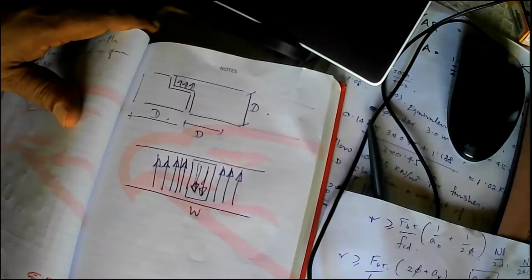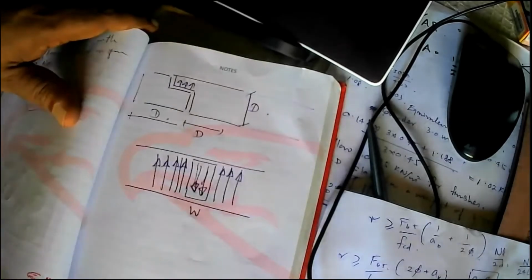If you are loading a beam from the bottom, then you have to make sure additional links are provided to transfer the load acting at the bottom level to the top level.